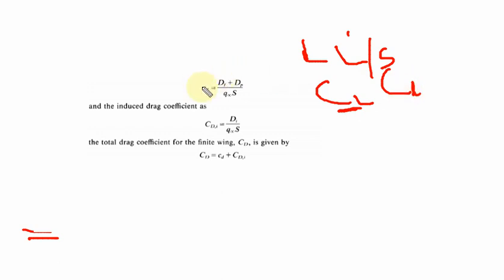So you see, in these cases we are considering only the drag value for the aerofoil, not a wing section. You must understand that this is your drag value for the aerofoil. So that is the profile drag. The profile drag includes your pressure drag and skin friction drag. This will be calculated from your aerofoil, because the aerofoil calculation is almost equal to the wing section. That is why we are taking capital D and small cd.